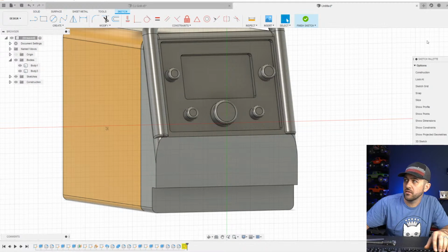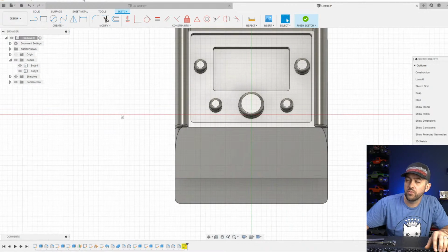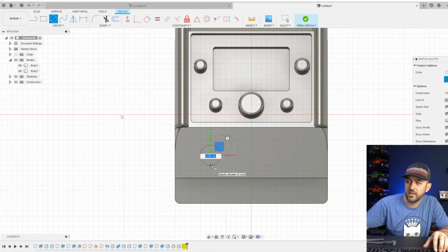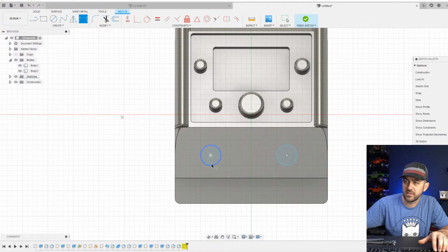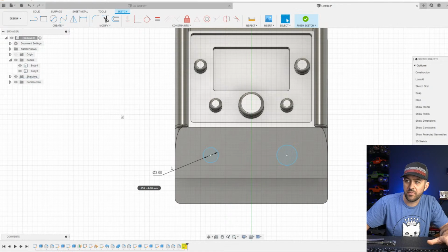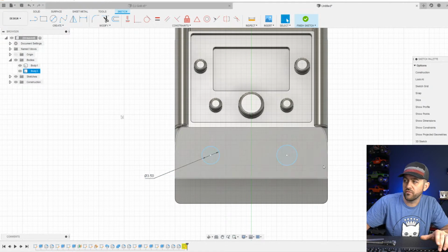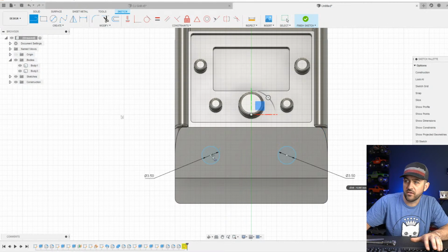We're going to go to this front panel and we're only going to put in 2 ports. Technically, there's usually 3, depending on the different types of whatever you're doing, or how your gas hooks up or your foot controls, things like that. We're going to keep this pretty simple. Now, rather than go right to the 2.5, we're going to go to 3 millimeter just to give yourself a little bit of room. Actually, I would even be fine with 3.5. Let's go 3.5, give you some room for glue and things like that. 3.5 gives us 1 millimeter over the outside diameter.